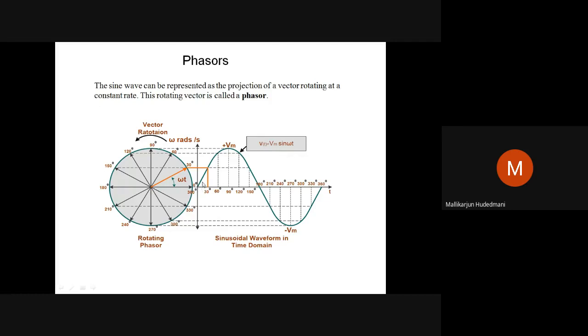And as the wave progresses forward, any instantaneous value at this point, this point, this point, how do we obtain it? Take the projection of this vector. This got shifted by 30°. Take a 30° shift, draw it, and put a torch from the rear side, from this side. The projection of this on the vertical axis, I have to measure this length. This length is nothing but, if I measure the shadow of this falling on the vertical plane, any instantaneous value of this quantity.